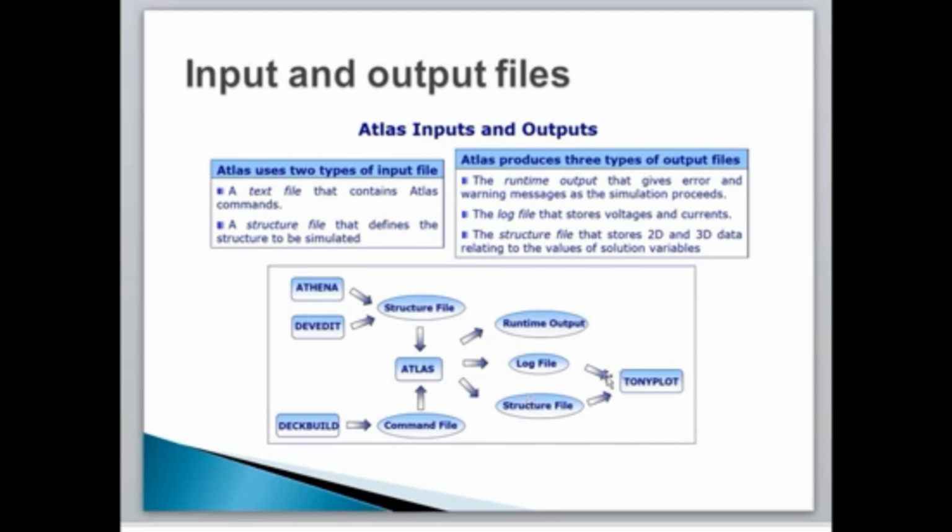Next one is Tonyplot. To view the result, the structure file as well as the log file, we use Tonyplot. Tonyplot is a graphical post-processing tool for use with all the Silvaco simulators and is an integral part of the VWF (Virtual Wafer Fab) interactive tools. Tonyplot can operate standalone or along with other VWF interactive tools such as DeckBuild, DevEdit, and MaskViews.